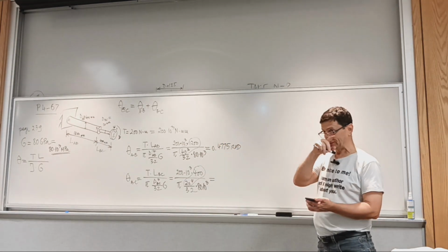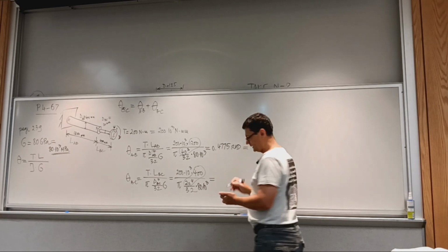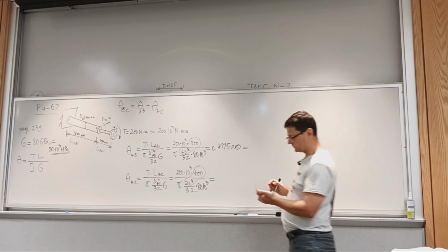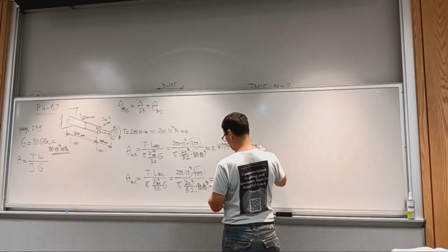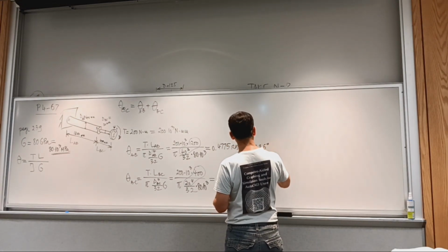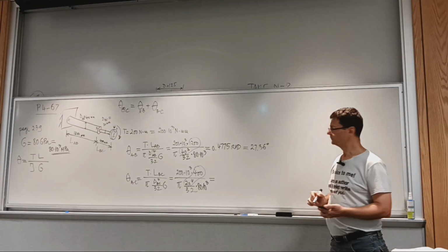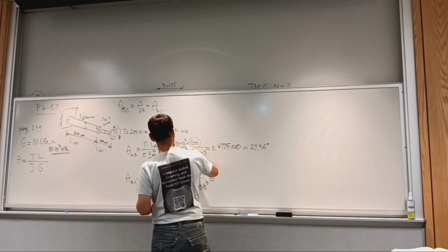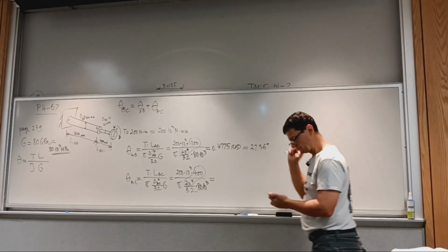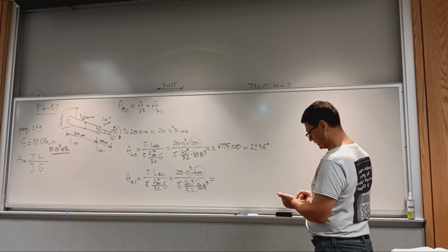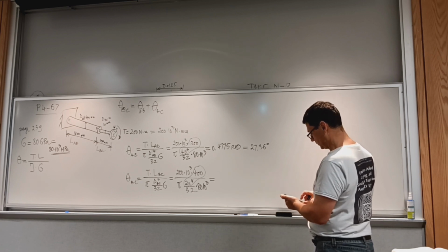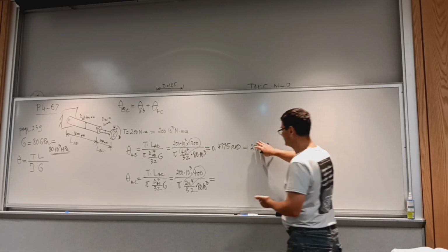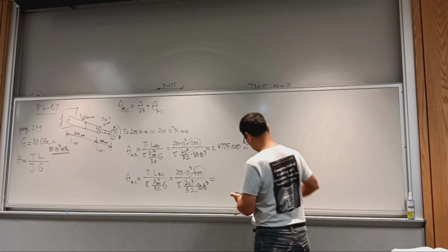If I want it in degrees, I need to multiply by 180 and divide by pi equals. So it's 27.36 degrees. Did I use 40 cubed? I think yes, I put it at power 3. So I can redo it. So times 1200 over 40 at power 4. Thank you for paying attention. This is still big. 27 degrees is a lot of twist.